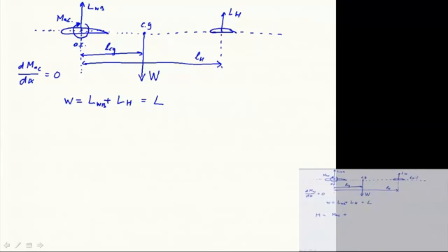Clockwise positive, yes, nose up. So we're looking at M plus, as you can see in the handout as well. M is plus nose up. So then we have to see what the lift is of the wing. It is also positive. Wing body times LCG, that's the arm. And we see that the lift of the tail is negative, and we cannot use LH there, but we use LH minus LCG. So this is the total moment around the center of gravity of all the aerodynamic forces. So is all clear?